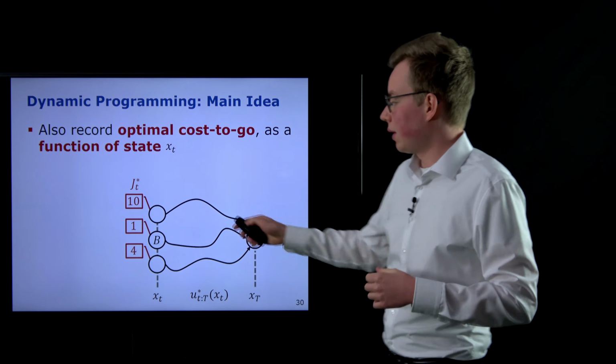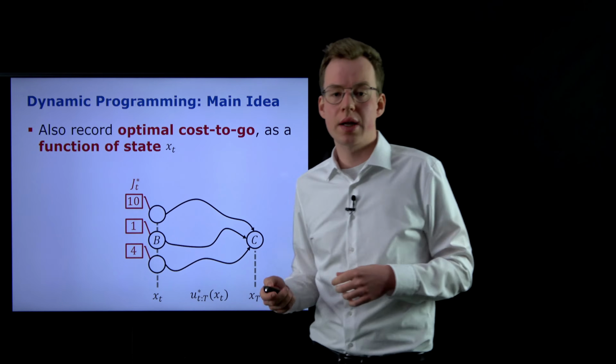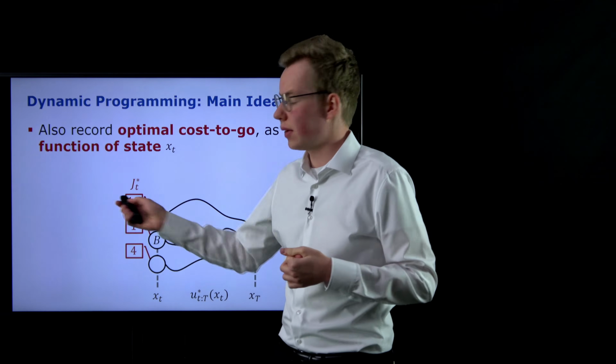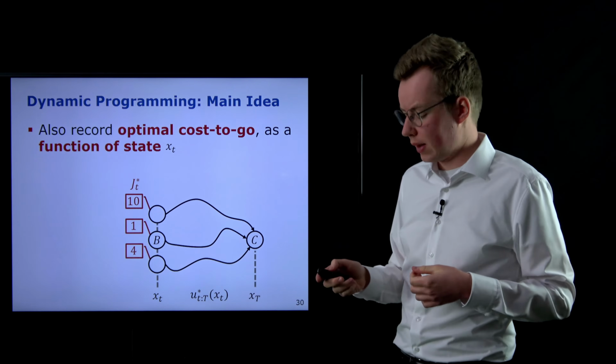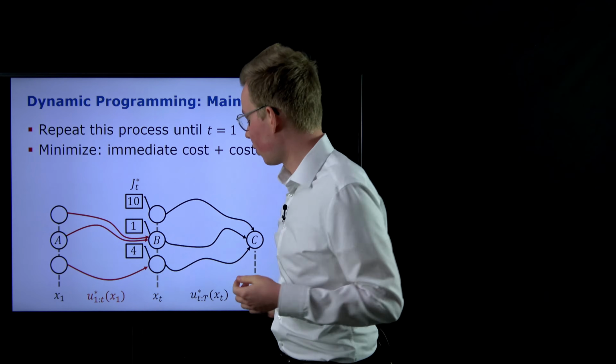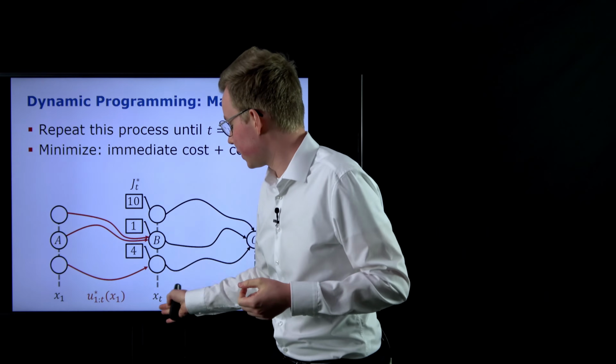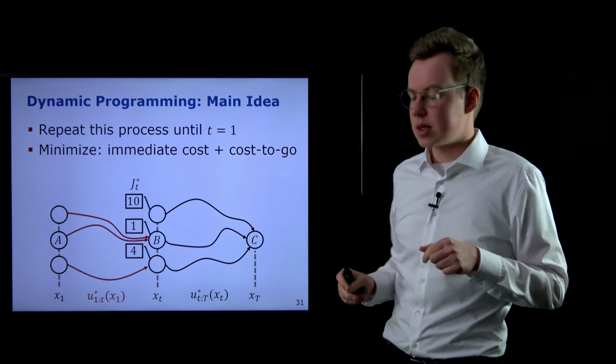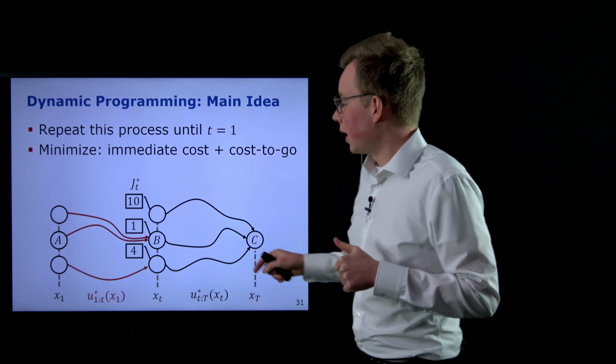And using this optimal cost to go, we can now extend the tail problem backward in time. Here we've just divided the whole horizon into 2 steps, so we have this intermediate time step and then the initial time, but technically you could also take many small steps.